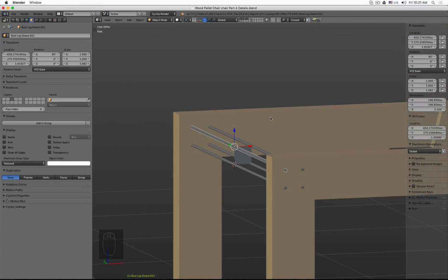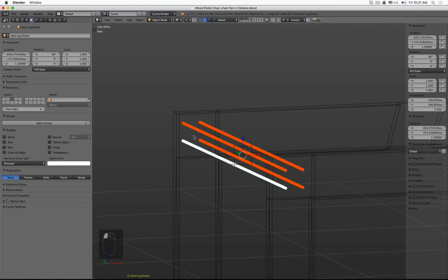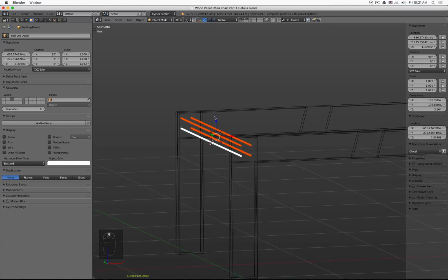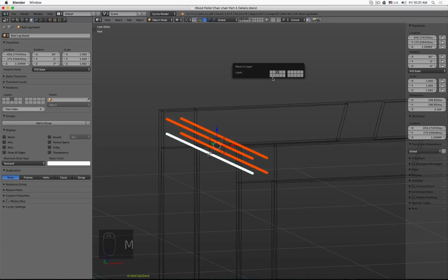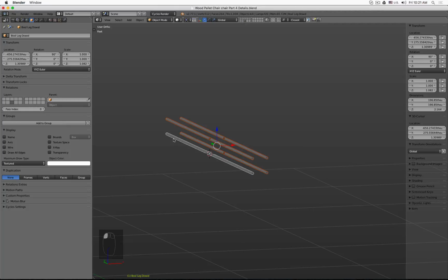So here's a little shortcut. And what we will do is these 4 I want to cut out of the individual wood parts, but I don't want to add 4 modifiers for each dowel to cut through. So we will do a small variation of how we use the modifiers. I call this one Boolean, so BOL, shortcut, lag dowel, so I know which one it is.